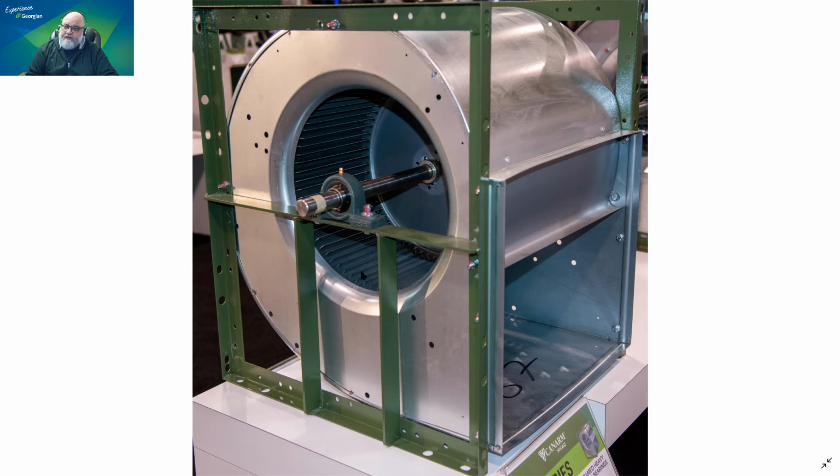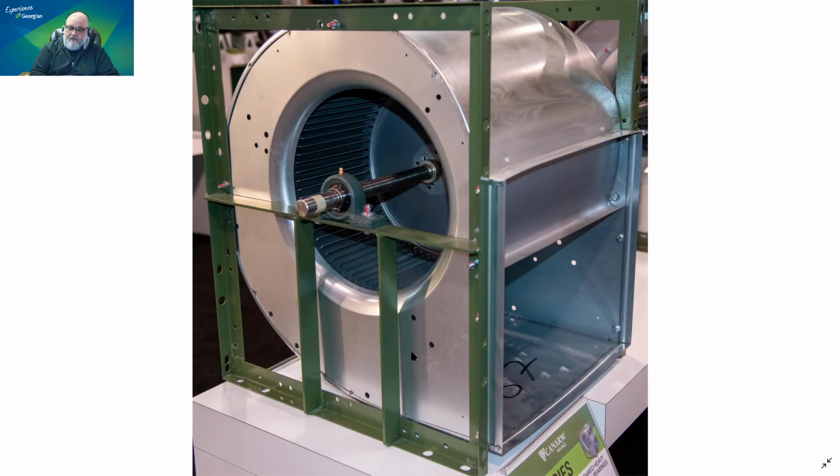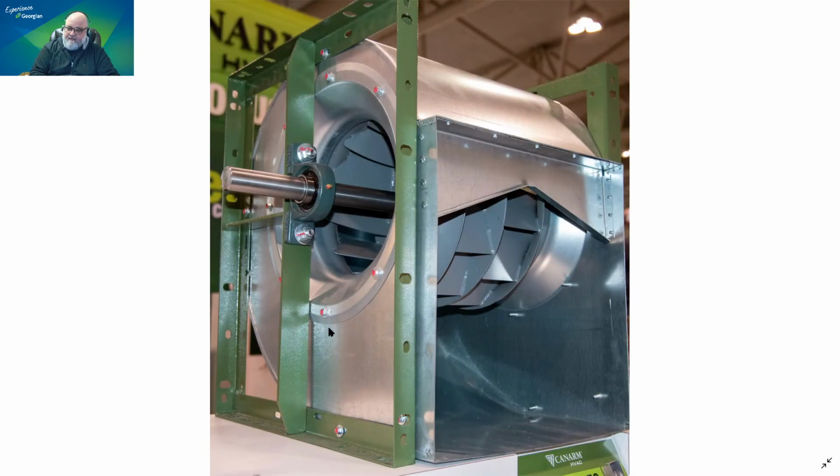So this wheel, when it turns, it scoops the air, it pushes against the walls because it is using the centrifugal force, and then the air has no place but to go out through this opening. So it is simply forcing the air out through that opening. If you look closely, there is this wheel here. Even though the structure of the housing of the fan is the same compared to the one before, as you can see, this is almost identical housing, but the blades are different.